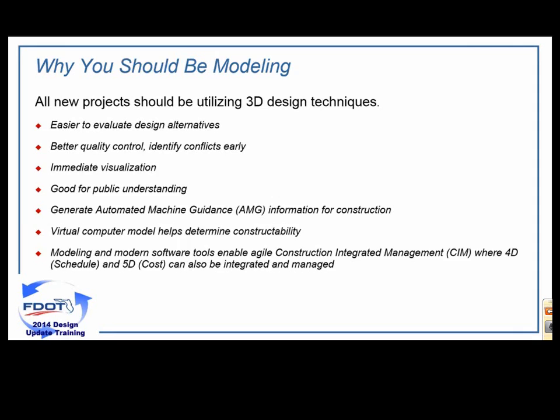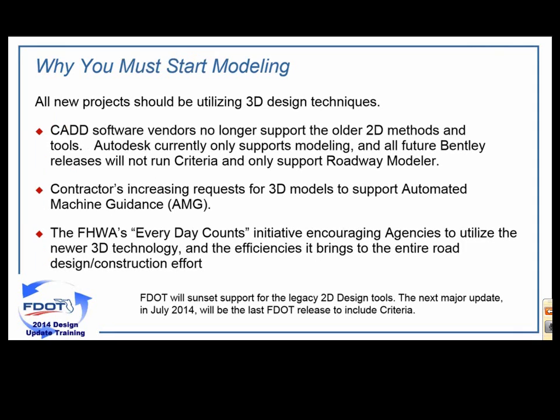Okay, so that's why you should be modeling. So why must you start modeling? And this is the big push here. All new projects should be utilizing 3D design techniques. It's very important. The CAD software vendors are no longer supporting the 2D methods. You're not going to be able to use criteria, for example, to cut cross-sections in the future. Autodesk currently only supports modeling with their Civil 3D application, and future releases of Bentley will also drop support for criteria. So the roadway modeler in that case will be the only application to actually do the roadway design.